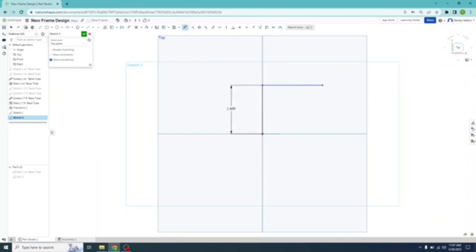So this is going to be the base of our right angle, so the connection we're making. And we're going to double click on the inches. We're going to set that at 2 inches for that first line. We're going to highlight the second line, left click, draw it out. Oops, I accidentally clicked twice. So I'm going down, I'm holding the left click button, and I'm drawing that square out, or rectangle, and again 2 inches. So now we have a 2 by 2 line, and we need to set the angle for it.